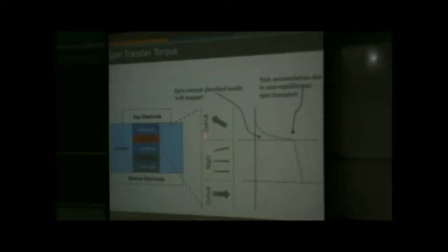And when they are going through the soft ferromagnet, they are getting absorbed in the soft ferromagnet. So you basically see a rate of change of the spins. That gives you the spin current. So you can basically say that the spin current is absorbed by the soft ferromagnet, that switches the magnet. And that's how the spin transfer torque device works.